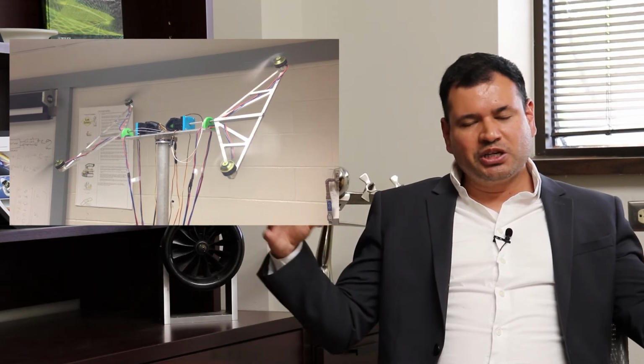I'll give you an example. In the video that you see here, we tried designing a mechanism that would allow transition for a hybrid vehicle. These rotor arms that you see in the video would be placed on the wingtips of the UAV. Through the control functions, we're able to control the movement of each of these arms. However, you'll notice that these are two separate mechanisms. In other words, there's no rod, no shaft that connects the arm from one side of the wing to the other. So it becomes very difficult.